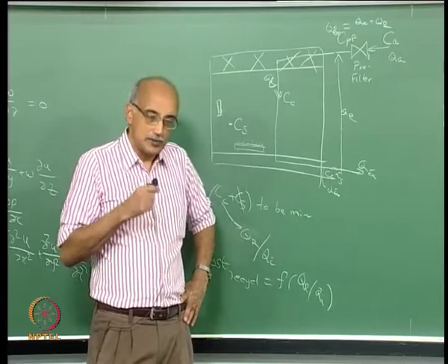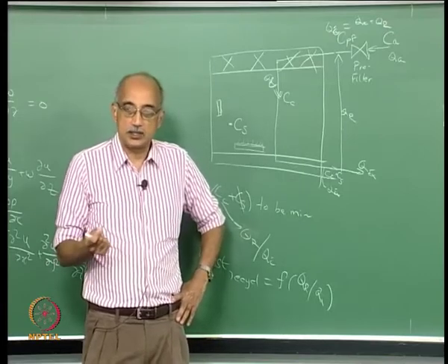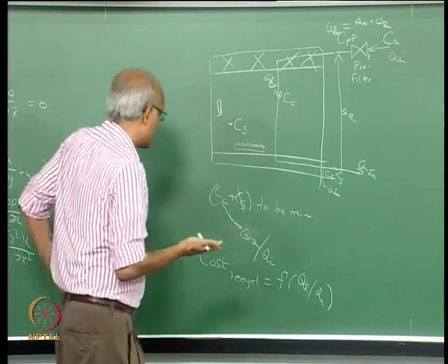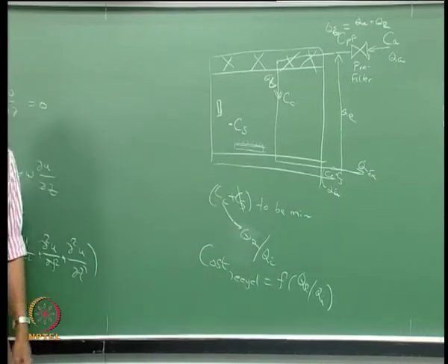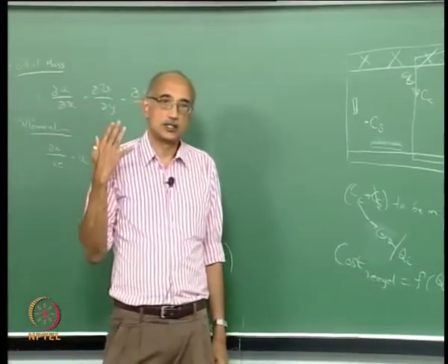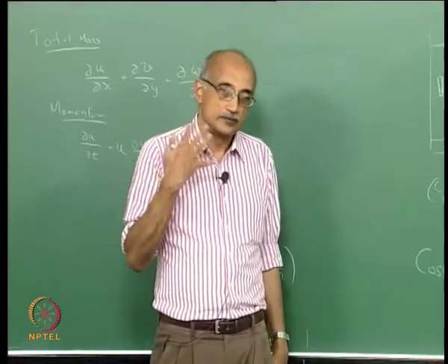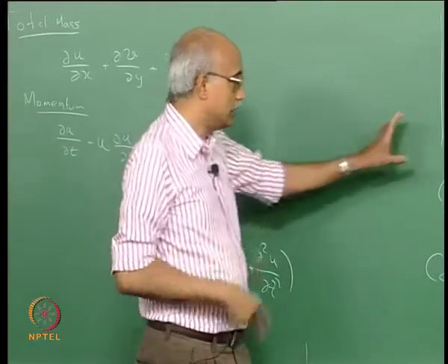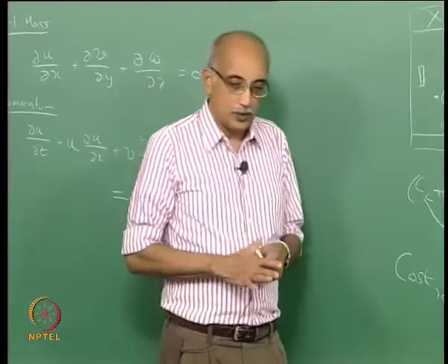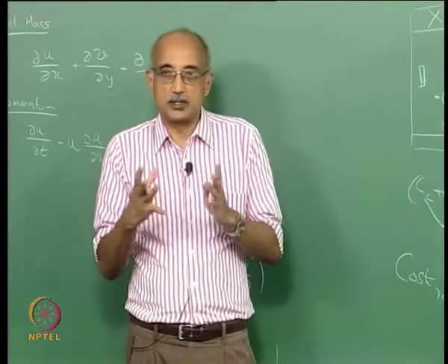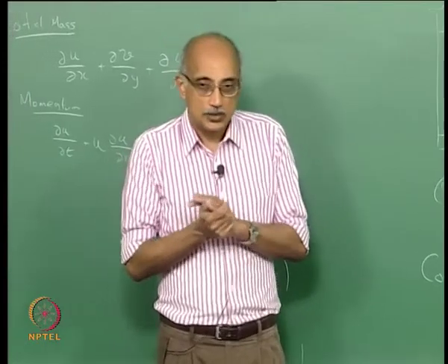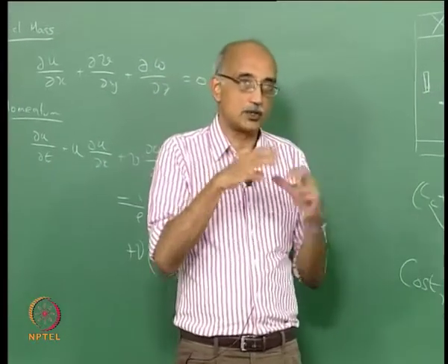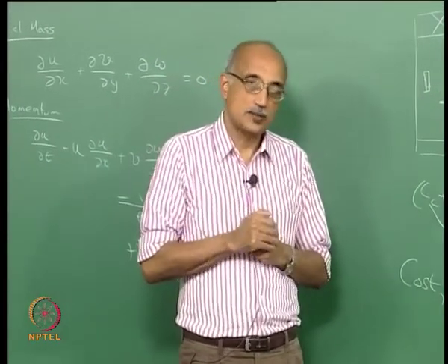And the time of exposure is critical because rate of deposition is essentially a time dependent process. The longer you expose the surface, the more material will deposit on the surface. So, even in a very, very dirty clean room, if you have a way of providing what is known as mini environments, these are enclosures that fit around the product that you are making, then you can actually protect the product.